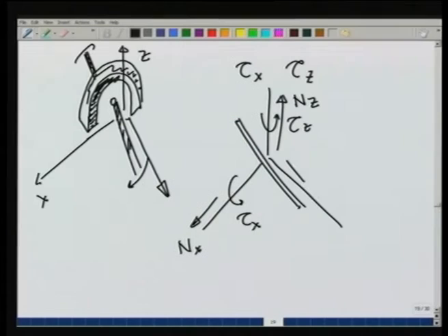In addition, if the shaft was completely fixed along the y axis, then it would also provide a force in the y direction. If it was not free to rotate, it will also provide a torque along the y direction. So, you can do analysis like this and find out what kind of forces and torques an engineering element can tolerate or provide for equilibrium.